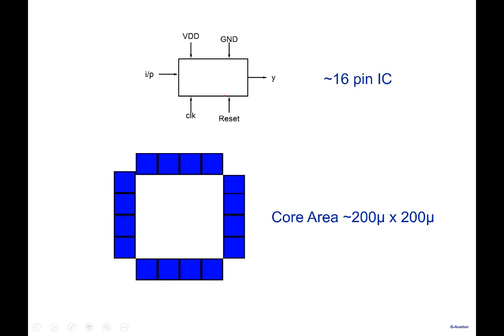So number of pins becomes very critical. You can see, it's not that you can have as many pins as you want. The pins eventually translate into the area and the cost. And remember also, a larger pin package will cost you more. A 16 pin package will be cheaper compared to a 28 pin package. So you'll have to pay more. So anyway, those considerations will come into the picture. But let's come to our main topic here.